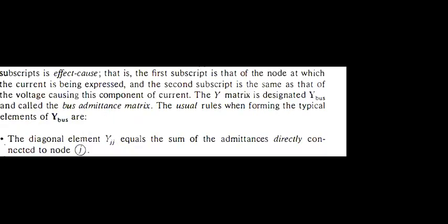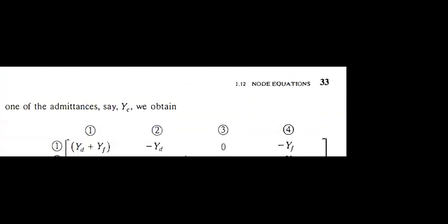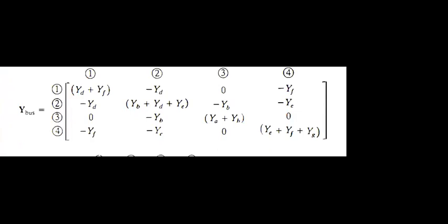So this is the admittance matrix formation of the given admittance diagram, which is Y bus formation by the inspection method. By inspection, how can we generate the Y bus matrix? When we have the Y bus information for any admittance diagram, we can generate Z bus from that. This is the Y bus matrix.